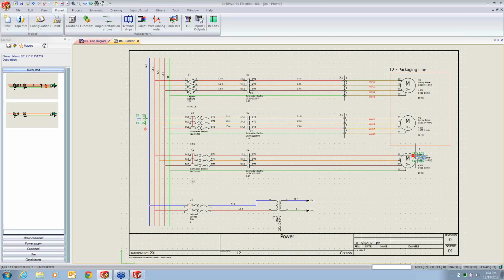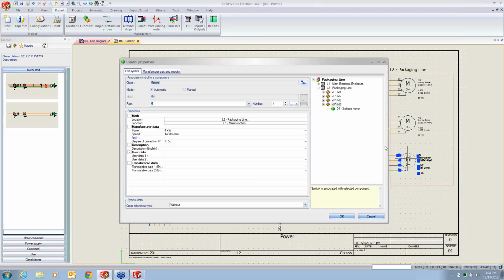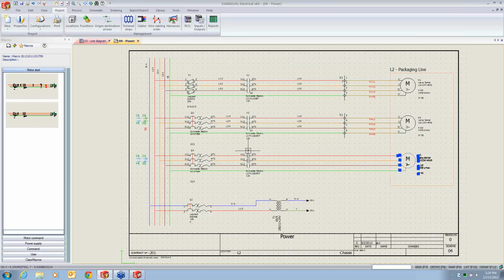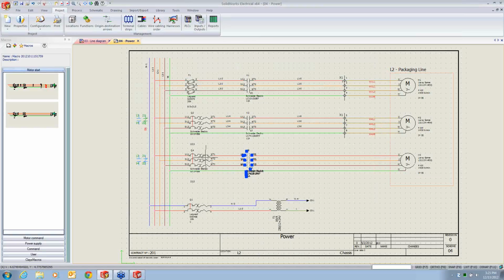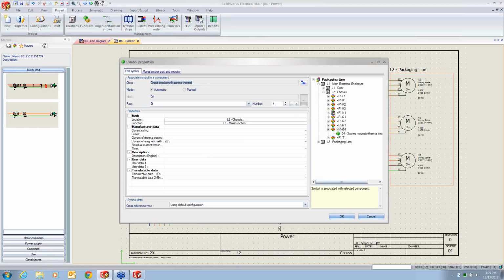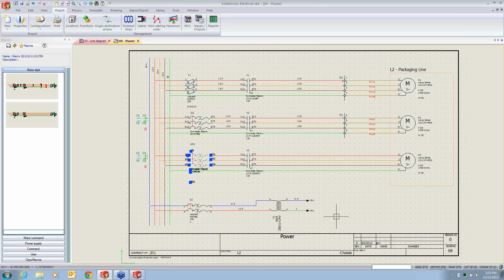Now if I take a few more clicks, I can come in here, update, make sure everything is in location 2, and then I can update this information to use the existing mode that I defined in the single line schematic. So we see here, I'm telling it I want to use information that I've already created. So just creating that single line sketch is updating information that's being shared throughout the system. This way I don't have to redefine things and duplicate my work, which could cause errors and other types of things along those lines.